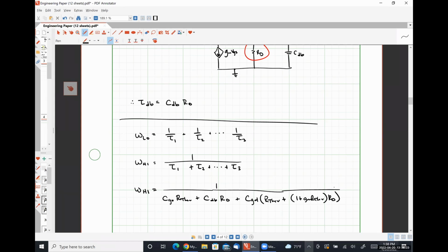Okay, so I'm going to give you a homework assignment on strictly common source amplifiers. One thing that I could potentially do here is put an output network containing a capacitor and resistor at the output and ask you to figure out what kind of pole and zero would be associated with that, or use the short circuit time constant method to see how that inclusion of a capacitor and resistor at the output node influences where the midband begins.